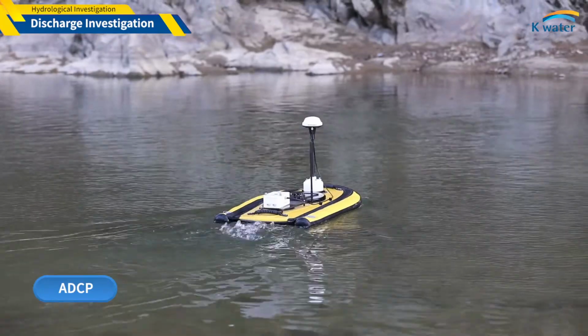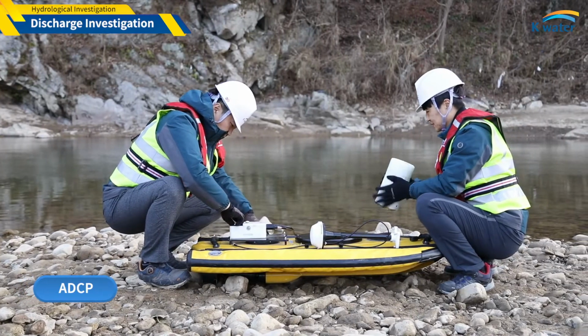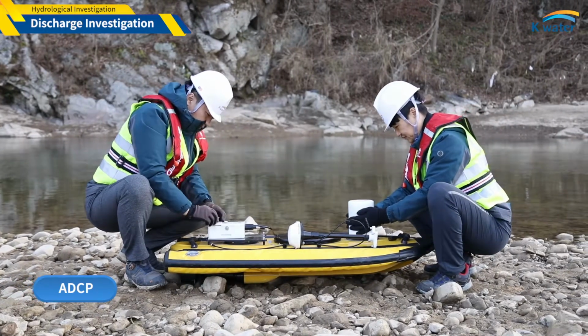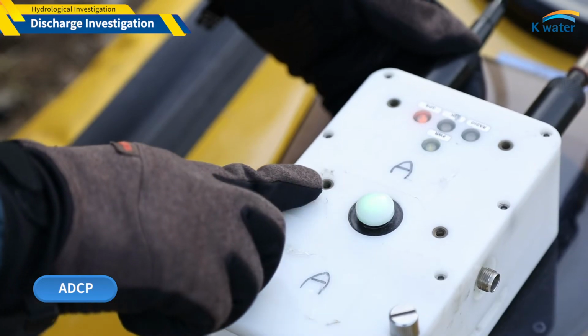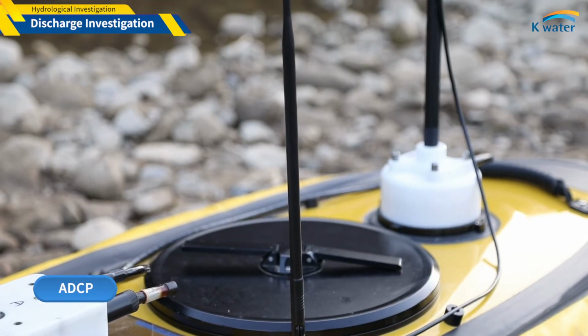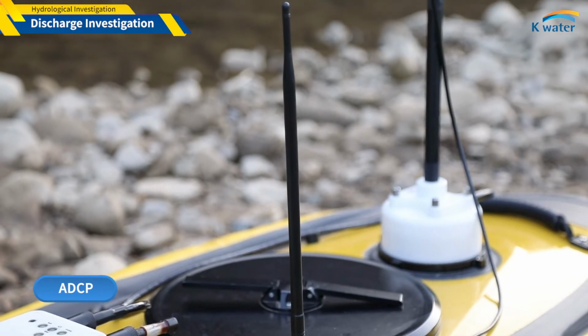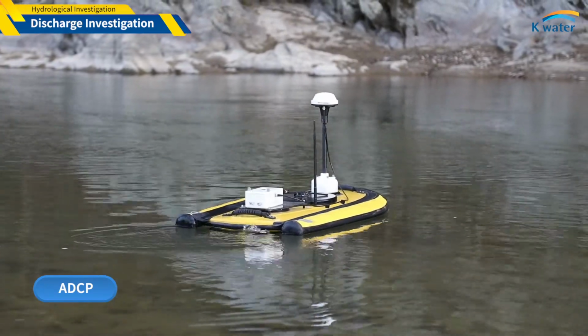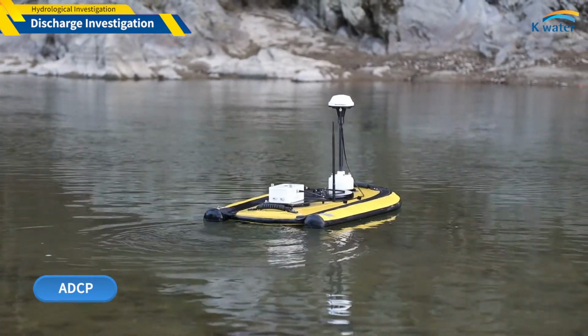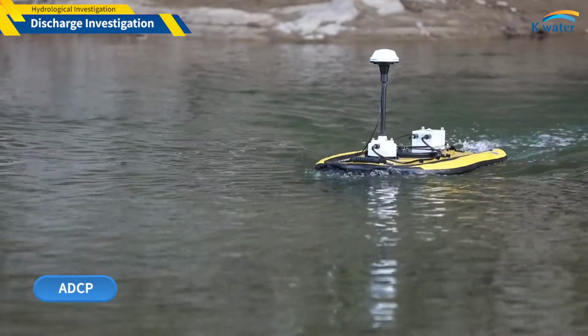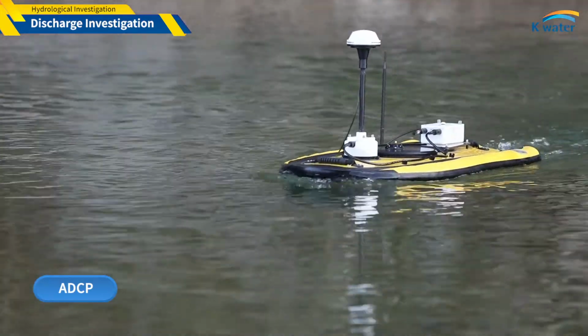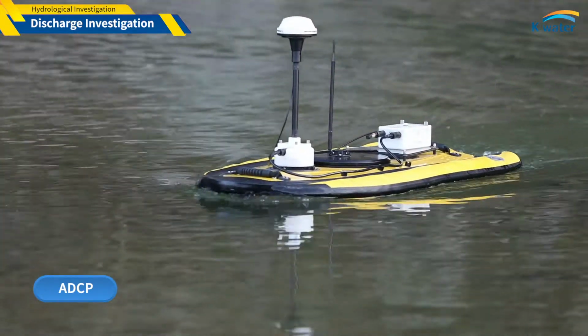It is measured across the river, so it is necessary to regularly check the condition of the sensor, the depth, and suspended solids, which can cause measurement errors. It can also quickly and simultaneously measure three-dimensional velocity distribution, depth, cross-sectional area, and flow, even on wide rivers.